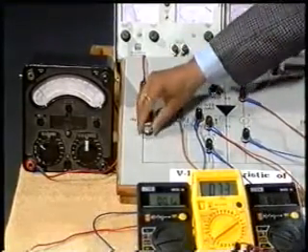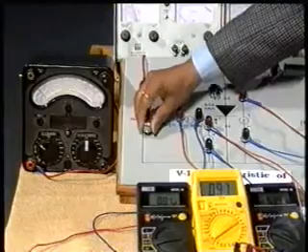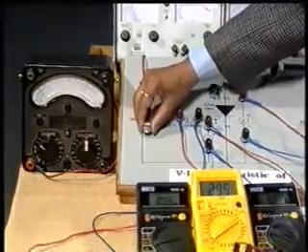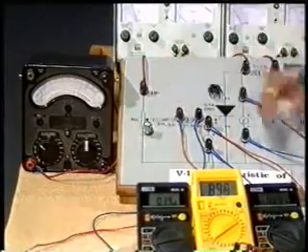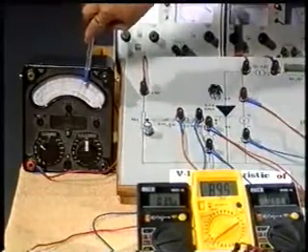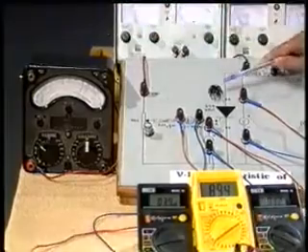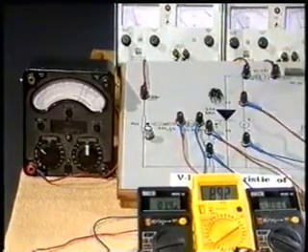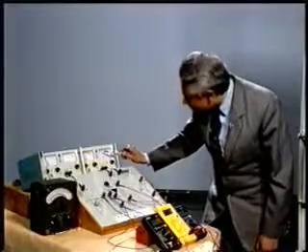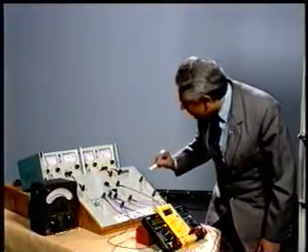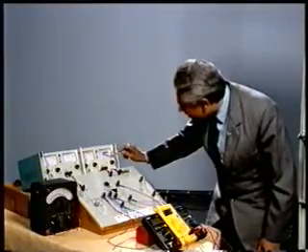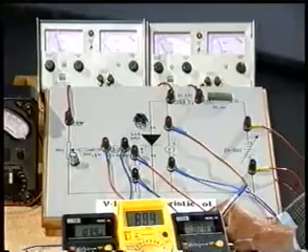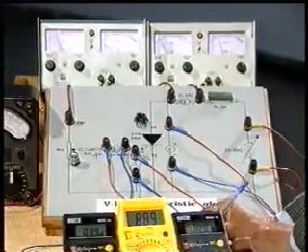So, I am again going to change it, and you concentrate on the analog black multimeter. Here, you see this has given you a kick. What does it show? It shows that this particular SCR has triggered. And now let us see the values. The maximum current has gone up to 650 milliamperes. I would note it down, 650 milliamperes.